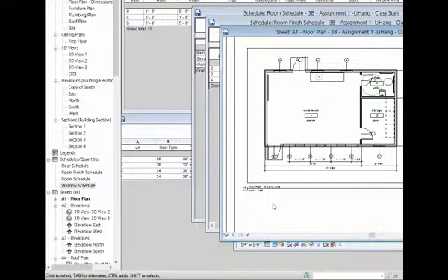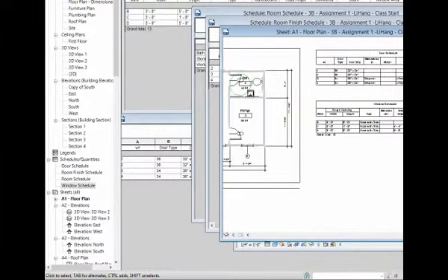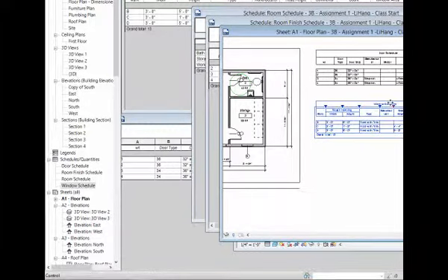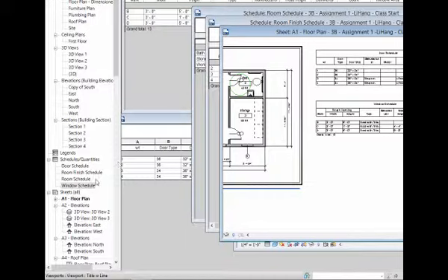It turns out quarter scale is actually a pretty good scale for most residential buildings. Even if I printed out this schedule here on normal size paper, that's probably 8.5 by 11 right there. So don't worry about blowing it up so that it fills the entire paper, because you're not making wallpaper. You're not making a poster to hang on my wall. Just allow it to be small and let it be, because that's actually a pretty appropriate size. But that said, let me answer your question, which is, if I do want to change